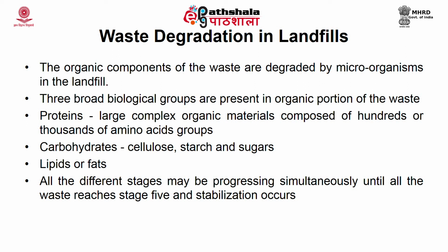Initially, the waste being deposited into the landfill will have some amount of oxygen in it. This oxygen will be used by the microorganisms present in the municipal waste, and this will lead to aerobic degradation. Hydrolysis, as you all know, is based on the moisture content, or the water molecules present in the waste. So, the first stage of degradation is hydrolysis or aerobic degradation, where aerobic microorganisms utilize the oxygen present in the void spaces of the waste.